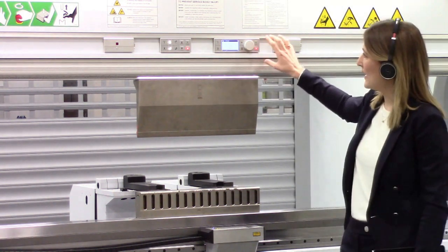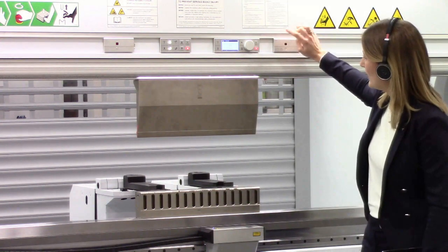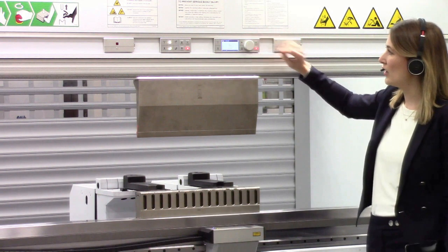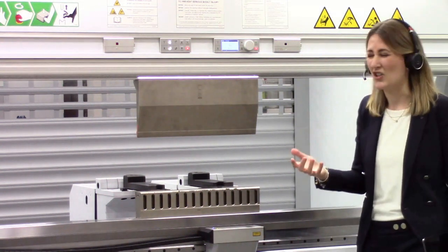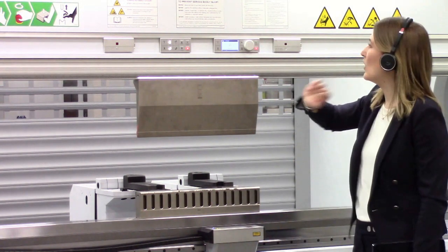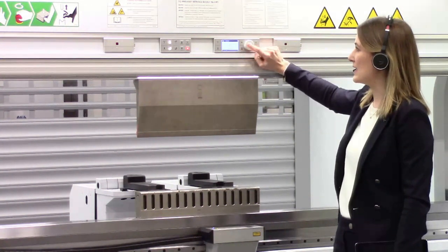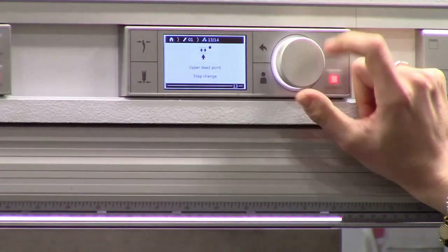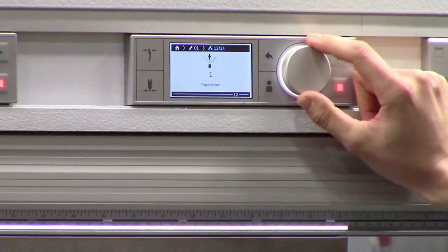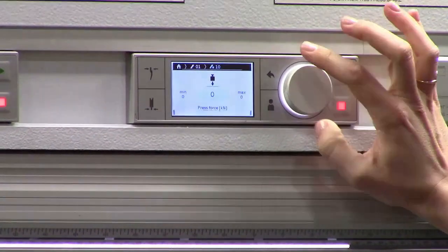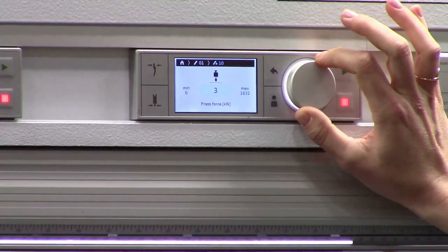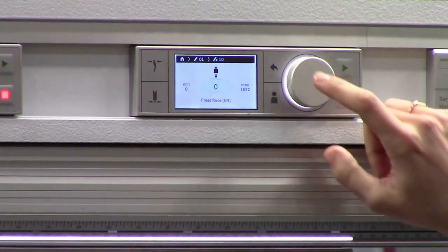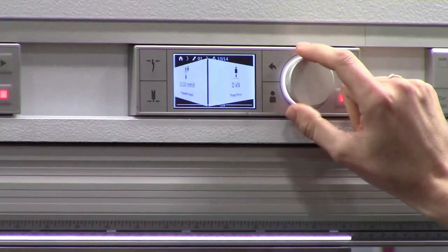The Mobile Control Pro on the other side is over here. There we have the same options, but we have a couple of enhanced functions, I would say. Here we can really make some adjustments right where the operator is. For example, you see here bending step number 1. We can go in there and have, I think, 14 different parameters that we can manipulate. For example, we could go in and manually change the press force. You see it's very easy with this little wheel that we have. And we could make adjustments to all the different bending steps.